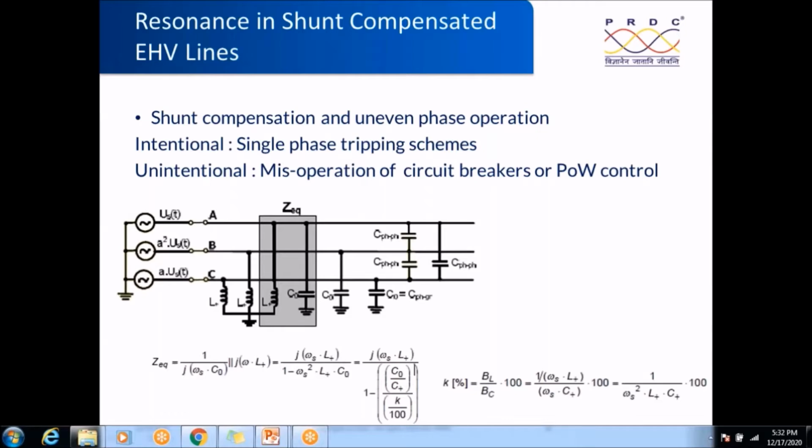So that is the ratio here. Looking at these values, this is the equivalent impedance, right? The top is J omega L, so it is inductive, but the denominator could be positive or negative based on the ratio. If it is negative, then it is capacitive, and if it is positive, then it is inductive. Okay, so that is the equivalent impedance.